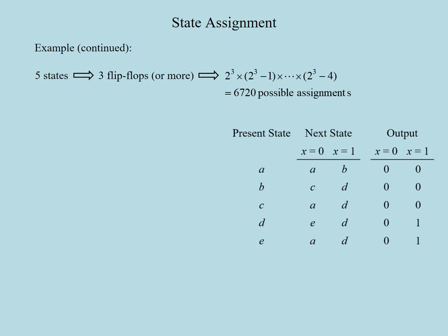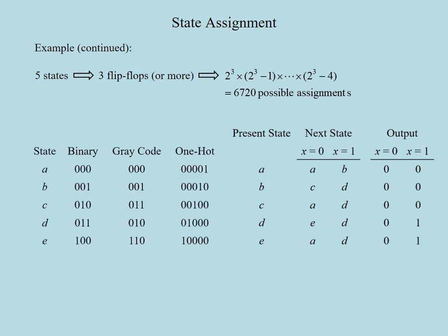Nevertheless, there are some commonly used assignments which may be generally advantageous in the design process. For example, you can be as simple as possible in choosing the state values and go directly for the first 5 3-bit numbers. Another possibility is to use symbols of a 3-bit gray code, which may offer some convenience in preparing your Karnaugh maps in the design process.